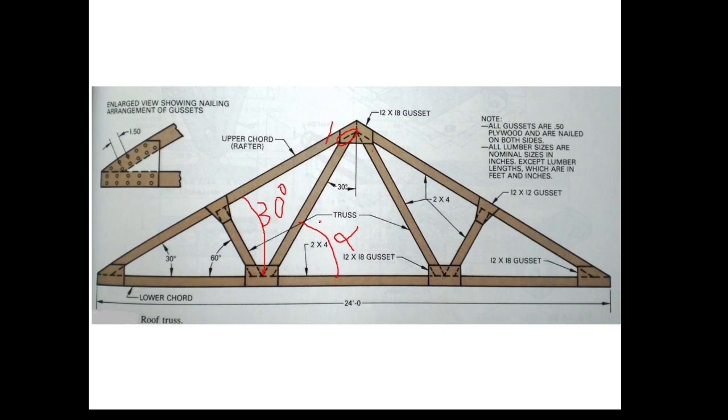Up to this part, it is a time-consuming thing, but not a difficult thing. But the difficulty is at the mating stage. Imagine you had the model of this member, you have the model of this one, and then be able to position all the members with respect to each other, to have the joint over there with the necessary inclination angles with respect to each other. Believe me, it is a challenge, not so easy a thing. Using the mating facility, if you do not believe me that it is difficult, at home, try. Create the models of the elements, have the models of the elements, just the basic, to their basic shape.